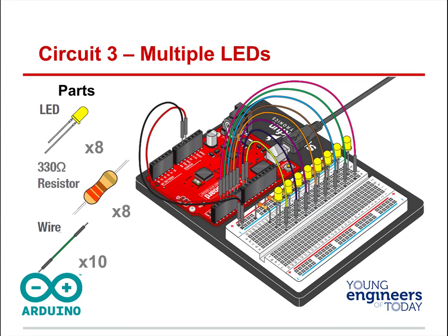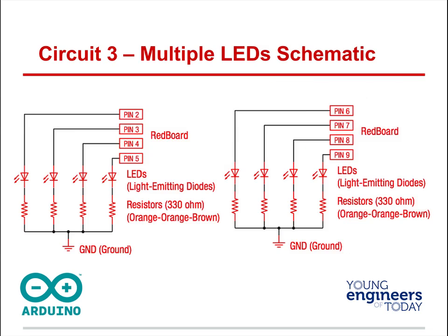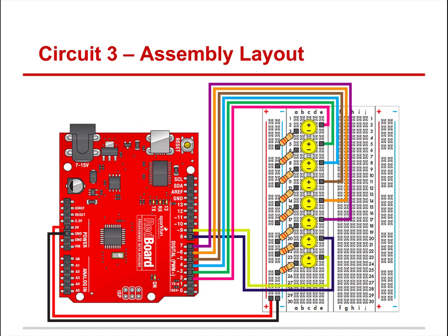So first, hardware assembly. We're going to put all the LEDs in, starting at pin 2. So we're at pin 2, pin 3, pin 4, pin 5, all these LEDs, and pin 6, pin 7, pin 9, and we're sharing grounds. We're using our 330 ohm resistors. Pretty much just keep expanding on what we've been doing. So there we are, going from pin 2 to pin 9. And we're really sharing this ground. The positive really in this is not doing very much, so we're just sharing the ground there.